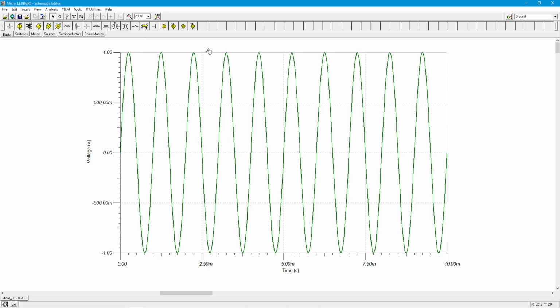It's kind of odd that you would actually hit the peak at any given point. I mean, you might, okay, but not necessarily. And something really weird can happen. Even if you have this thing on a regular ISR, an interrupt service routine, it just might work out that you always take measurements at the same point in the cycle.